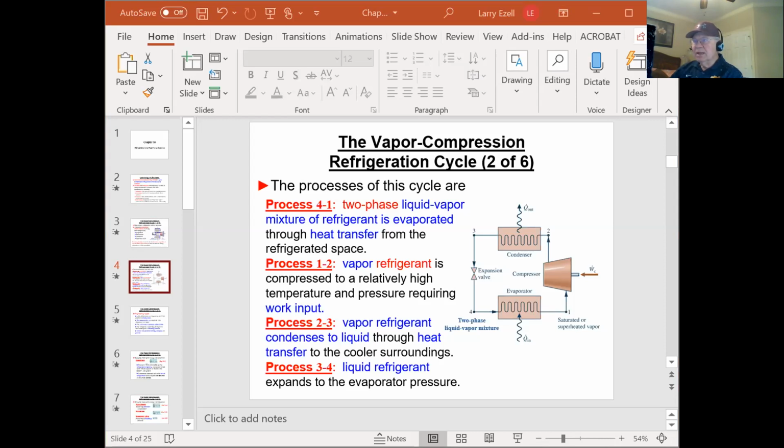All right, well, let's look down here. Here's about 60 degrees. So I would choose an evaporator pressure of about 70 pounds per square inch, between 60 and 80. That would give me 58 or 59, around 60 degrees. Now let's look at where I would want the higher pressure to be.